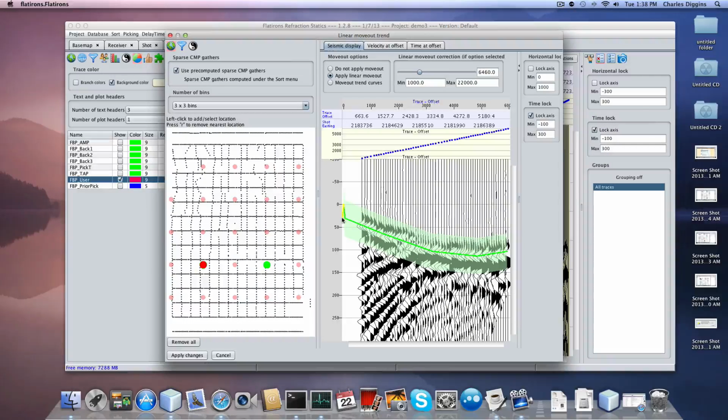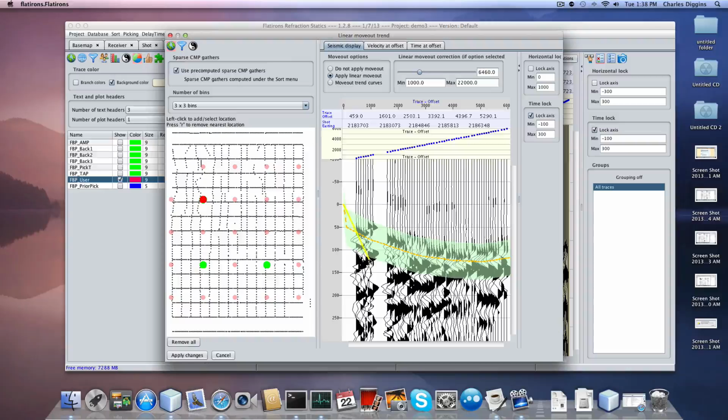I prefer to start off, as you can see here, where there are no traces, because if I just went from here to here and another gather has traces in here, it would interpolate from 0. So I'm projecting back to about 30 milliseconds here. That's just my personal style. Let's look here. As you can see, it's now starting to interpolate the guide function.